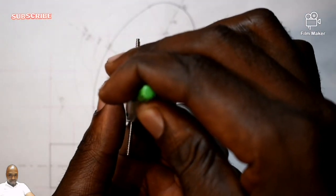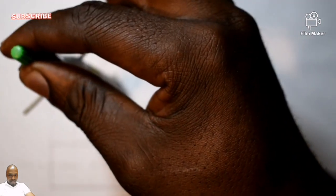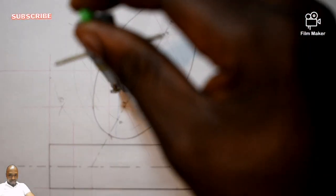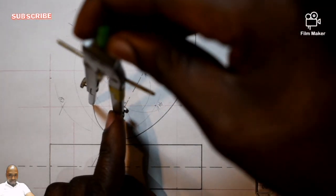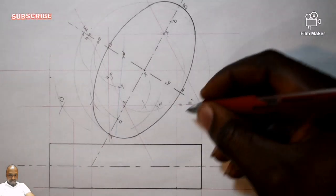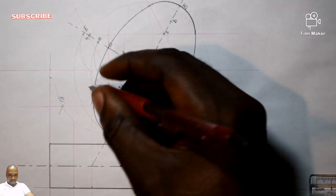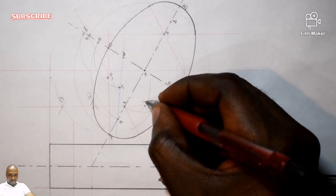Just open a little bit. Then I'll strike an arc somewhere and strike an arc somewhere there. Then I come and place it at small letter A. I bisect these arcs on top there and on top there. So I've got the second point of Roman figure 1, and there is our Roman figure 2.